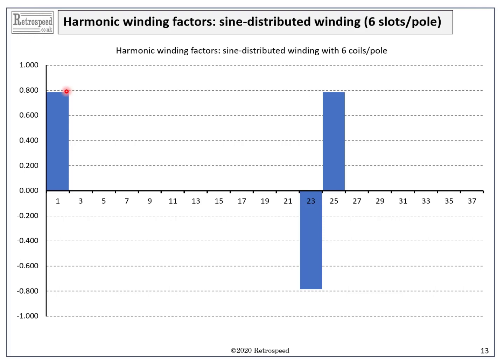These are called the step harmonics. Sometimes they're called the slot harmonics, and their order is the number of slots plus or minus the number of pole pairs. Although their effect in producing flux harmonics is inversely proportional to their harmonic order, as well as the winding factor, they can be troublesome, and the point to note is that they always have the same winding factor as the fundamental, and so they cannot be eliminated by the choice of winding distribution.